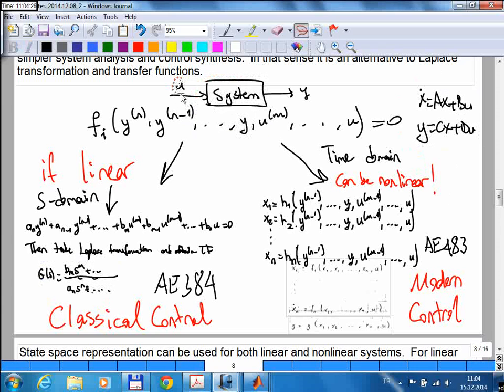For example, if you apply an input and if you want to calculate the output, the output you calculate from here should be exactly the same output you calculate using this mathematical model for linear systems. Okay, so here, if the system is nth order, the transfer function has an nth order denominator, which means there are n poles for that system, right? So we talked about these poles before. So these poles are related to this matrix here, and this is explained in the lecture notes.